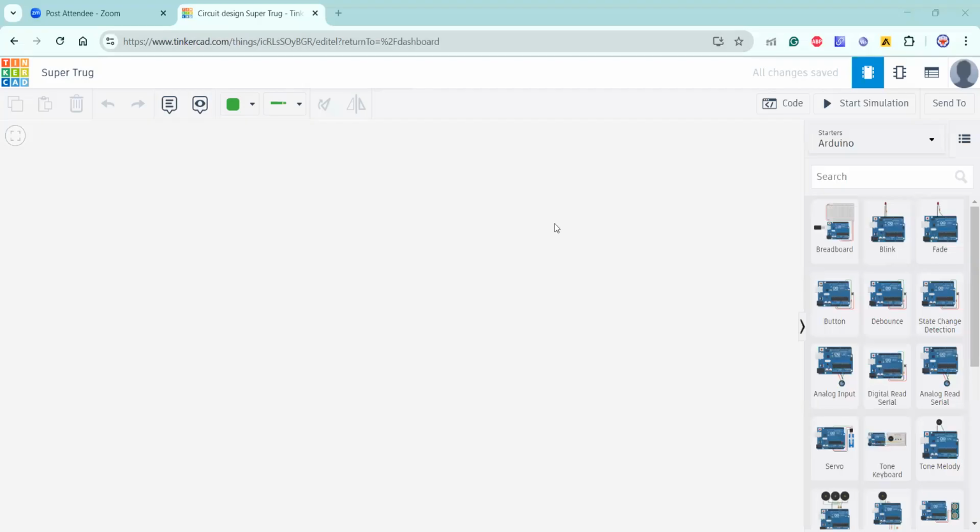Okay, thank you. So what I'm trying to say is, once you log into the Tinkercad software, you will get an option called Create on the right side. If you click on that, there will be three different options. One is for 3D designing, another is for circuits, and the third one is for code blocks. As we are dealing now with Arduino and microcontroller stuff, we should choose the option called circuit to build our own circuits. If you click on circuit, you will find this kind of screen with a basic component on the side.